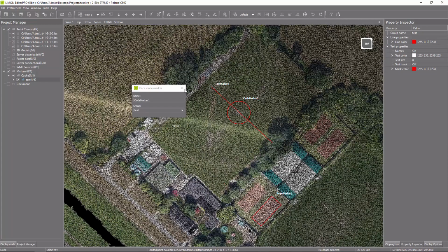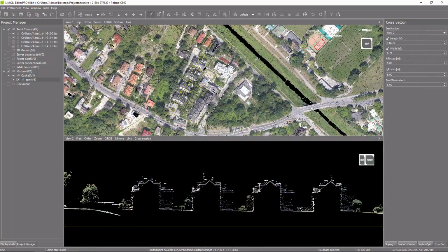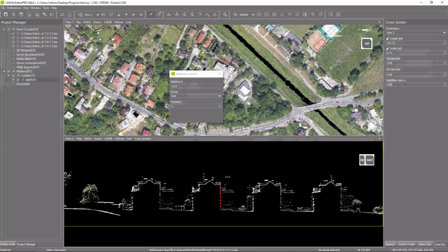To operate on such markers, it is best to make a cross-section to have access to a fragment of the image on a side view. With a height marker, it's possible to select the number of precision digits. To check the altitude between the points, simply click the left mouse button at the selected points. The marker shows the height of the second point relative to the first.